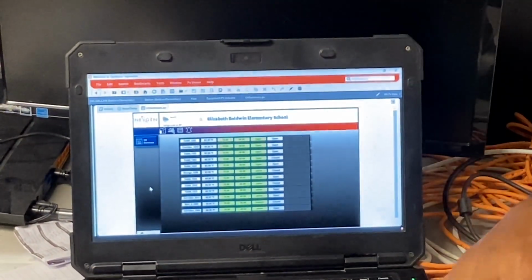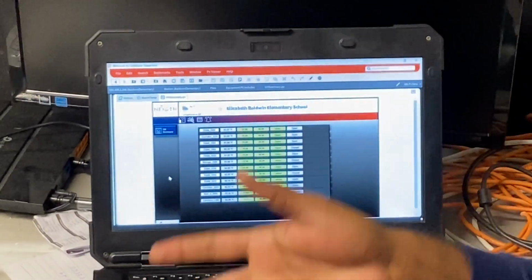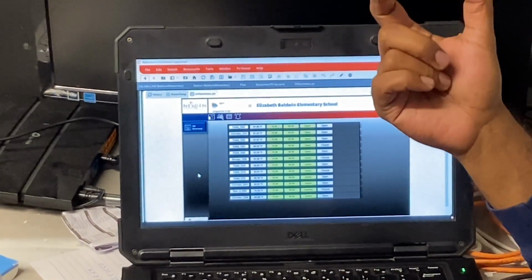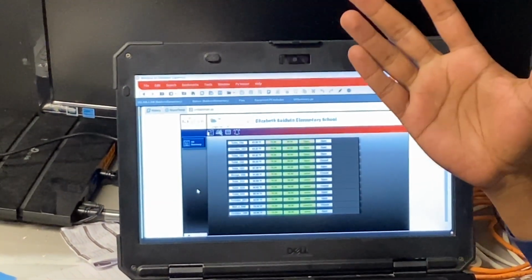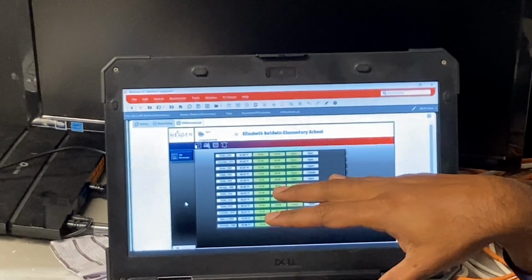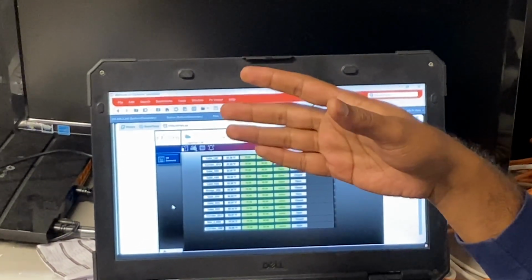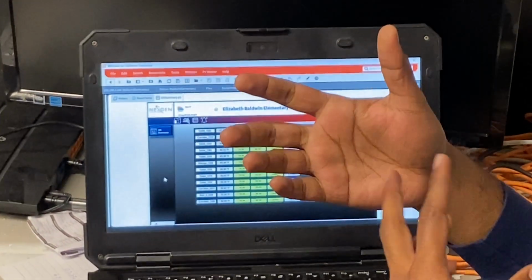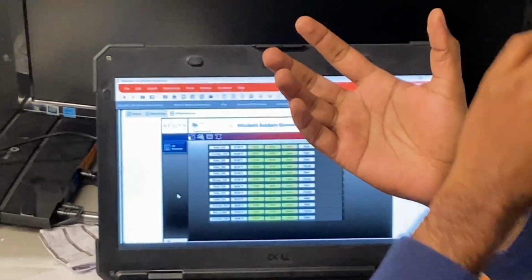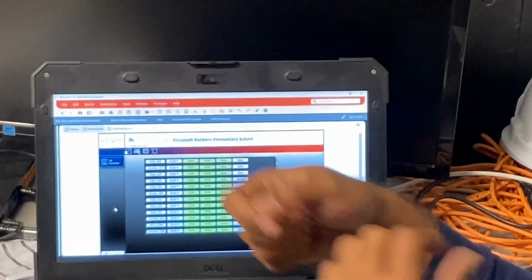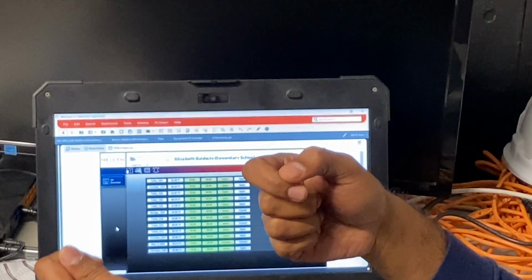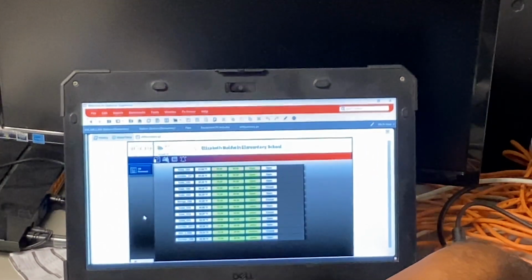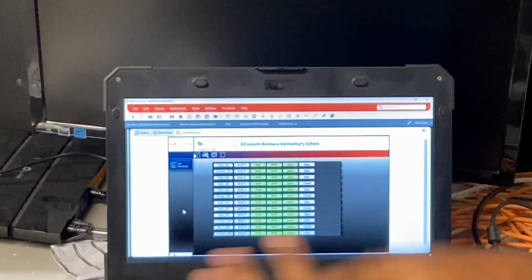If the temperature goes below the set point, we open the valve. All the unit heaters are on-off valves, two position, either on or off, controlling the space temperature. We open the valve and the aquastat senses the heat and turns the fan on, and we get the fan status. That is all the unit heaters.